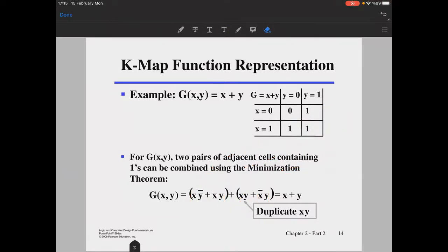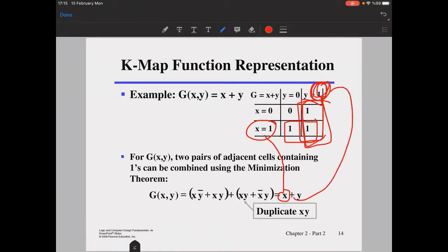And how about size 2 rectangles here? If you go ahead and have 2 rectangles like this, the first one is x, and for the other one, you see y is constant here and x is changing, so it's dependent on y, and you just add the minterms. That's how we do the sum of products representation that we discussed in the previous session.